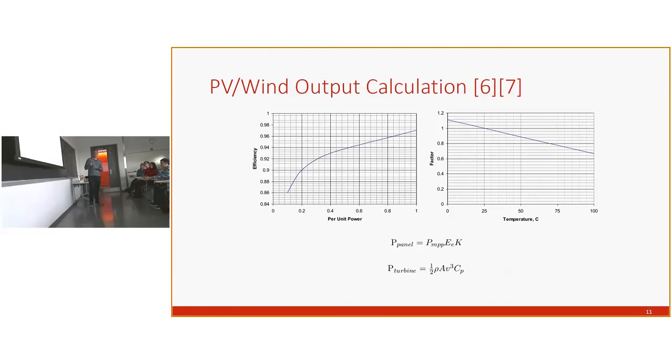These both will come from the manufacturer of the device, and so they give you that this cell has a nominal value of 1 at 25 degrees Celsius. So the cooler it gets, it generates more power. The warmer it gets, it generates less power. And then these equations will dictate the power being produced. This involves the temperature, the irradiance or sunlight coming down, and this constant value here depending on the temperature.